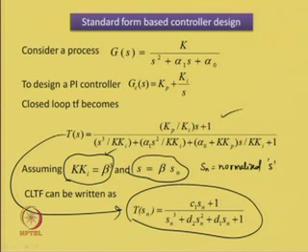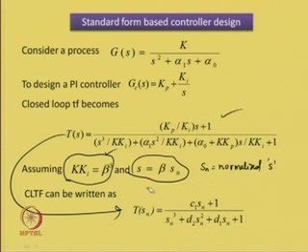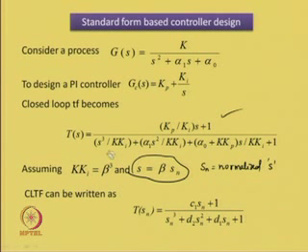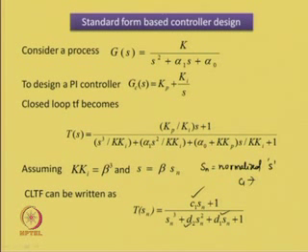This standard third order transfer function has 3 coefficients, namely C1, D2 and D1, and we know that for any given C1 it is not difficult to find D2 and D1 by optimization of some standard criterion often known as integral square time error criterion.